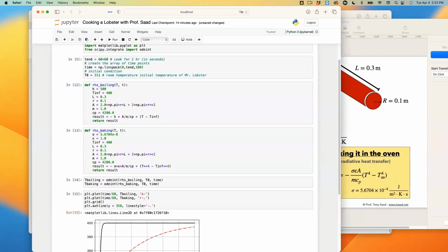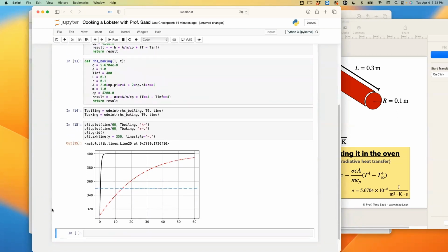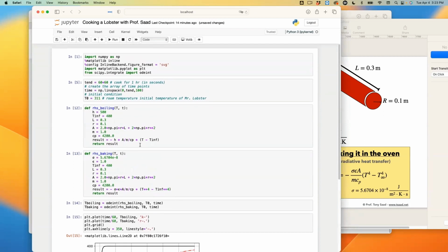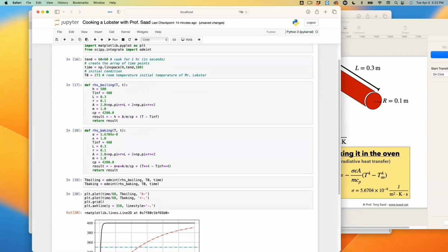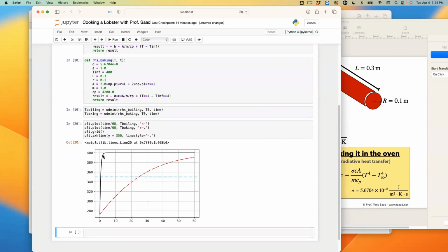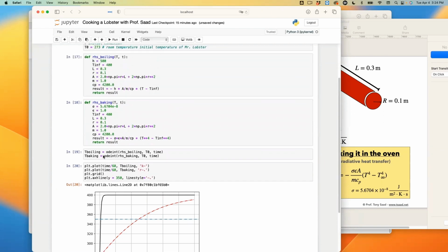Now when you solve it, look what happens. This weird fluid gets it done in like 1 minute, which is very unusual, so probably that H was very, very high. If you can design a fluid that has such a high H, then you can do it. Now let's go to freezing temperature, like your colleague Todd said. Let's go, I don't know, 273. Todd was saying that it barely made a difference with such a high heat transfer coefficient.